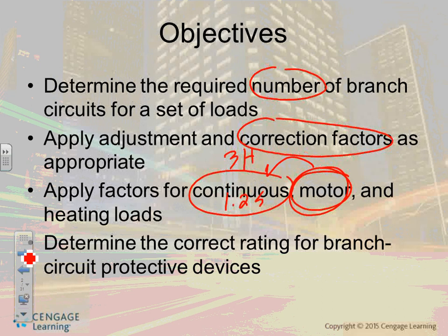Motors are also, can you guys write yourself a note? Motors are always considered continuous loads. Always. Heating loads are always considered continuous loads, right? Think about it. There is a pump. Don't you think the pump will run more than 3 hours? So you have a heater, right? Baseboard heater. Any type of heater. Do you think the heater could run for 3 hours or more? So heaters and heating loads, and motors, are always continuous load.